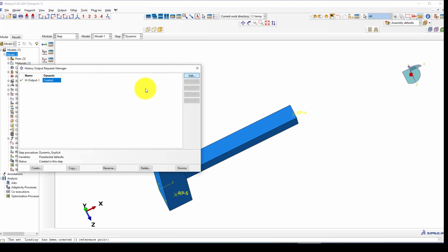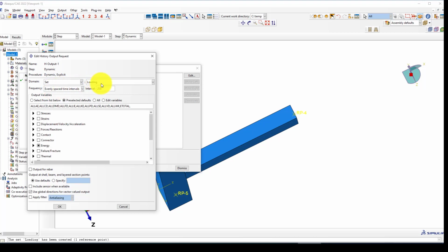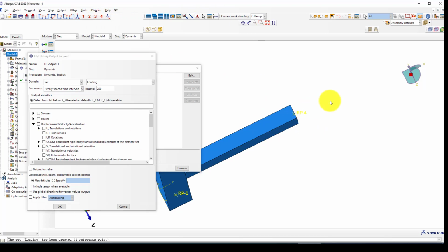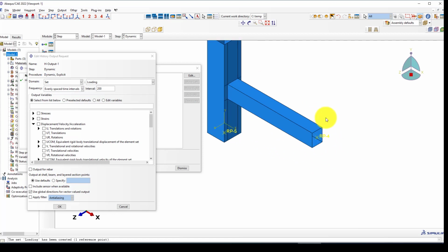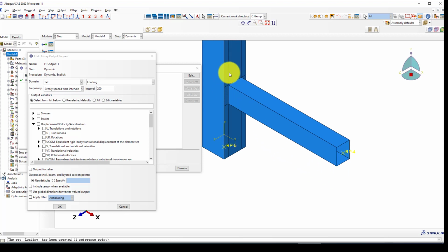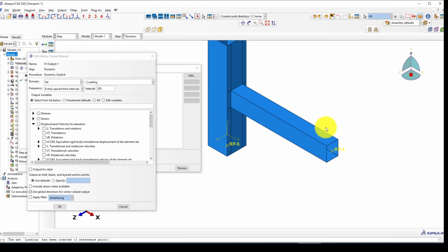and here is the output. I want to create an output using that set loading, and here I want to get it in 200 intervals, giving that displacement in the vertical dimension and the actual force in here. Instead of applying some concentric load, we'll apply displacement. So we push until the total disconnection fails. So then we will measure the displacement.